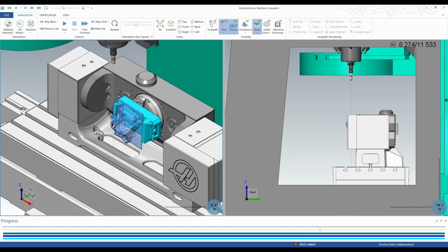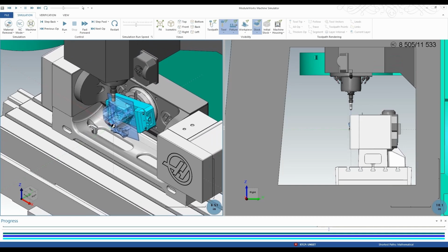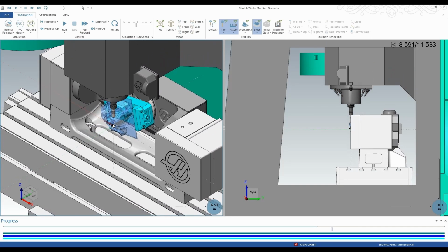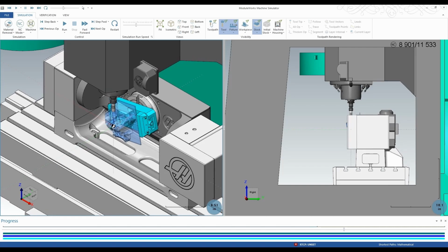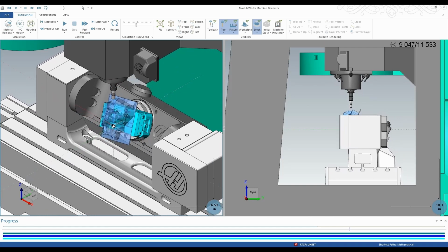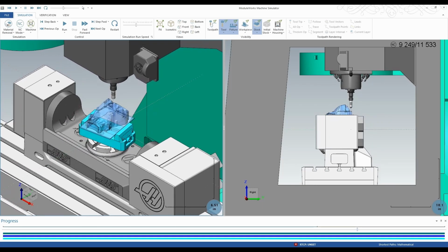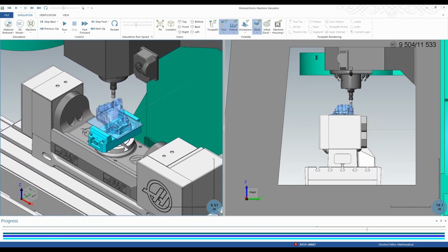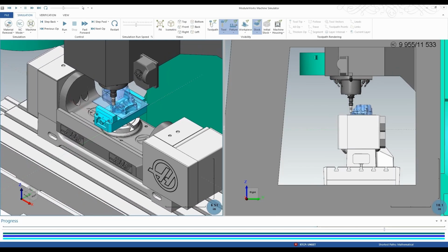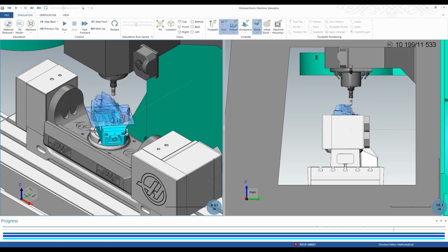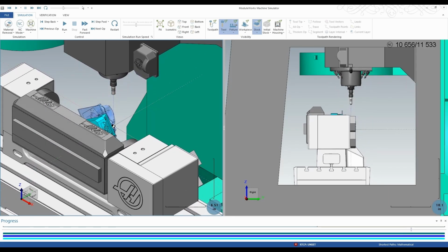So here's the next toolpath that we just processed. As we go along here and start drilling this part, you'll see that our transition moves are forcing that down following that wrapped shape. Especially here as it rotates up, you'll see that the tool follows that part. It never comes all the way up to its high retract planes. Follows that up and follows that down, maintaining that wrapped surface as its safety boundary.